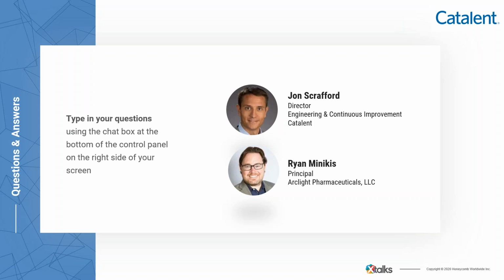It's a great question, and it's really a very common issue that needs to be dealt with. So the first recommendation would be to ensure that you have a robust solution preparation process where the polymer and the API are completely dissolved. The biggest risk is having any undissolved material in the feed solution, whether that's polymer or even some extraneous matter, which can easily clog that small nozzle orifice.